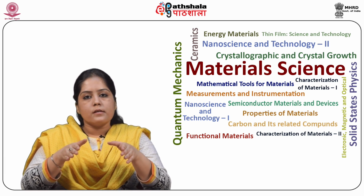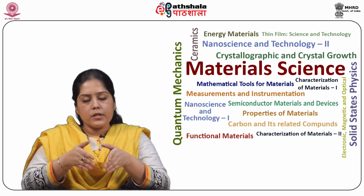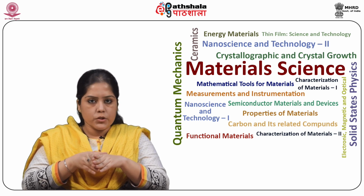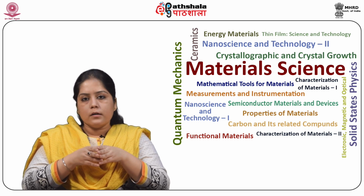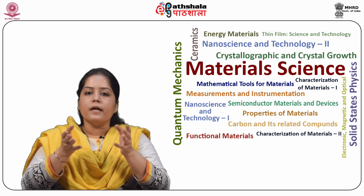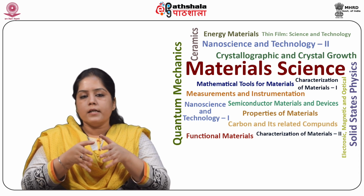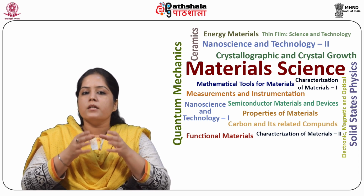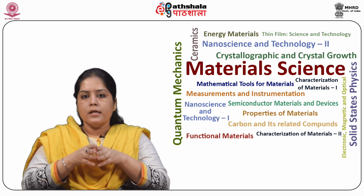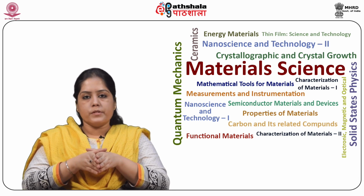Other processes like molten phase formation, oxide evaporation, and liquid metal oxide formation may also occur depending on the environmental conditions and the material system. Oxygen-induced embrittlement of matrix materials is also known to occur in some systems.